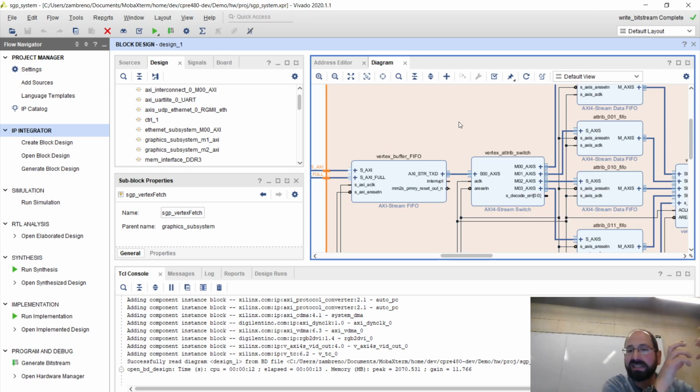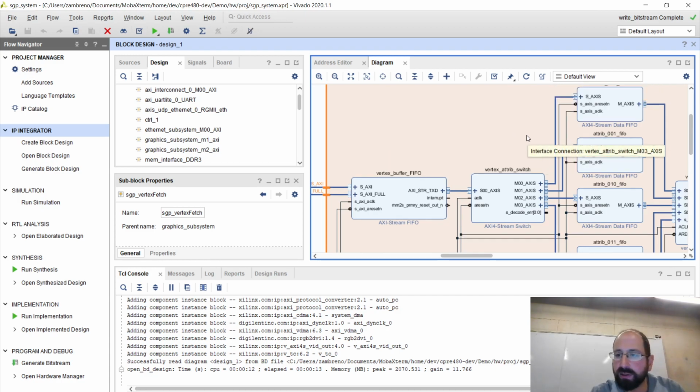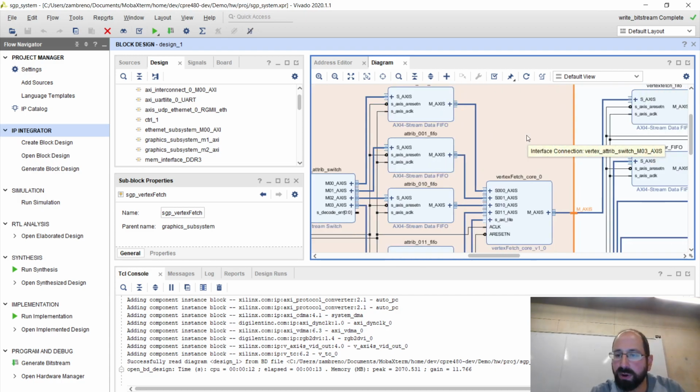And you'll need an AXI full, AXI 4, AXI memory map labeled port associated with that. And it's also very common that you're going to want to configure and or read the status registers off this IP core as well. And for that, we can have an AXI Lite interface. So I'm looking to see which core individually has both.